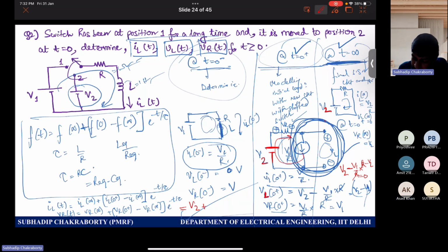Whenever you have doubt, you just write KVL. That KVL to the direction. But one thing, when you have assumed one direction at the start of the problem, don't change it. That's why you should be experienced enough to choose the correct direction, right? Now, how do you choose the direction? By seeing the positive lead and assume as drops. If it is not a drop, then it will give you the negative of that, and you will go ahead with that. It will automatically give you that sign. So don't change the convention. You keep writing, the mathematics will actually tell you the answer.